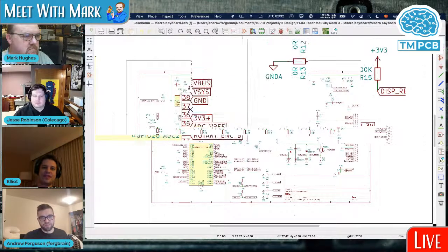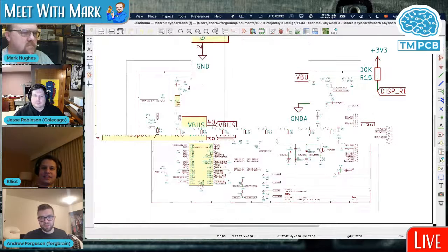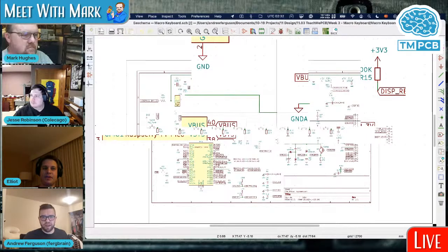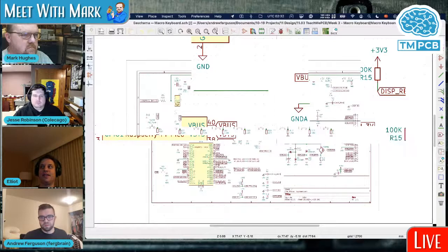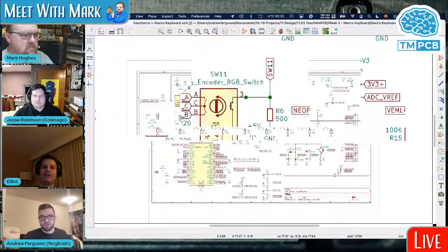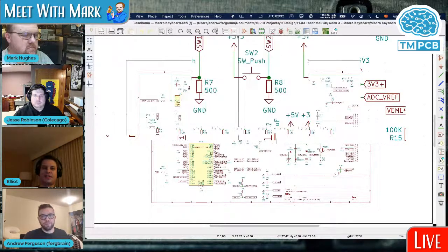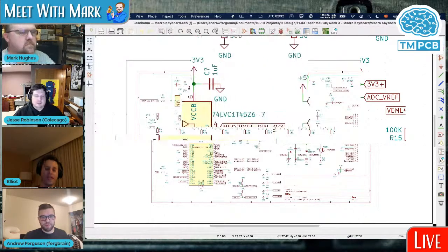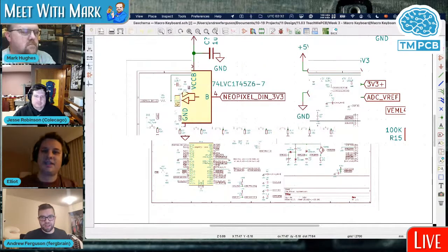I use global labels because they terminate, and so I would know that that was sort of the end of the line. I guess if you have a line like that, you can have a wire going off to nowhere with only a net label, and it is okay. Well, no, I know you can have it, but from a visual standpoint of did I forget to connect something, it's helpful to have a terminator.